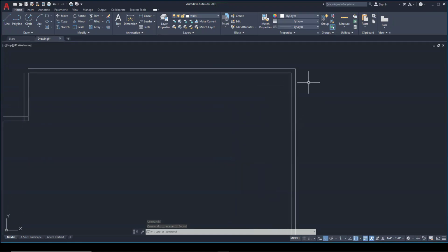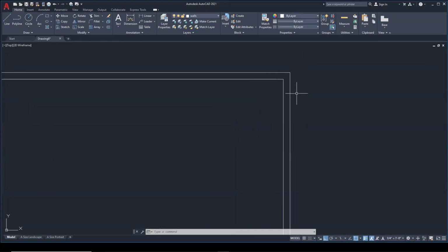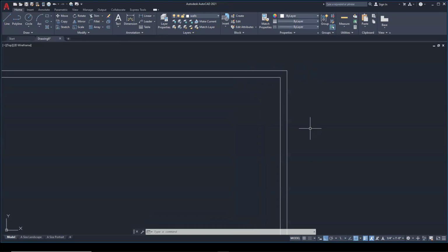So that is two ways to fillet. There's a square fillet and there is a radius fillet. So if when you're working in AutoCAD, for some reason, you're getting radius corners, that's how you can resolve that. Again, fillet command, this time I'll just type F, enter, and then click on radius, and you can change the radius. By the way, you'll notice that up here, where it says select first object, it shows the current fillet settings. The mode is trim and the radius is set to 0.